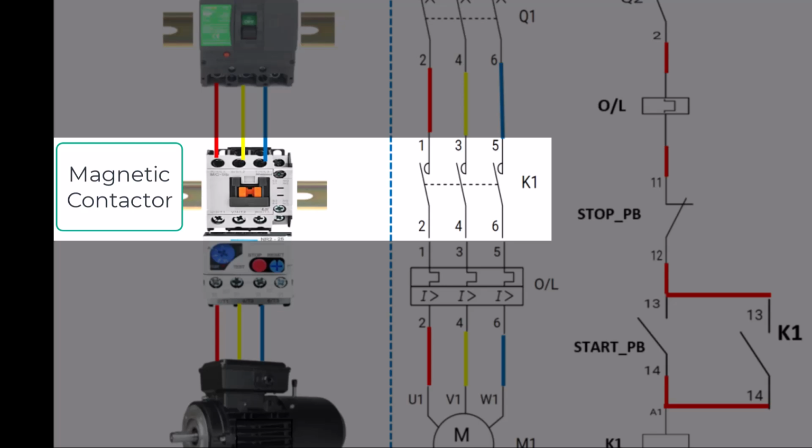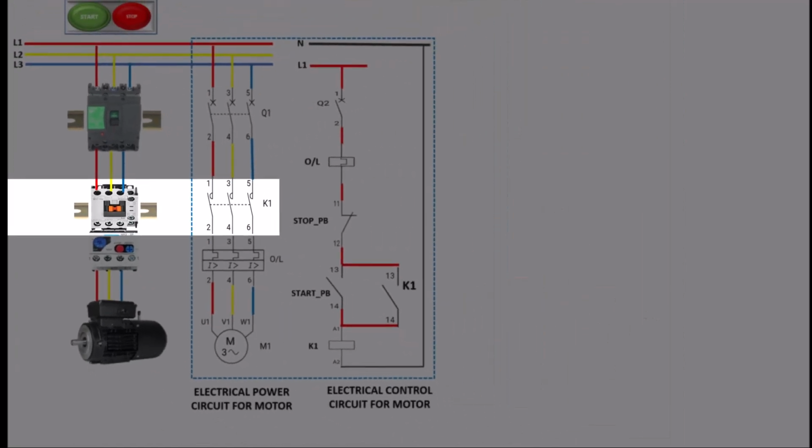When the push button, or PLC, sends a stop signal, the contactor disengages, cutting off power to the motor and safely bringing it to a halt. Additionally, many contactors feature auxiliary contacts that provide feedback to the control circuit, indicating the motor's status and enhancing system reliability. This functionality is essential for precise control in automated processes while maintaining safety and efficiency.